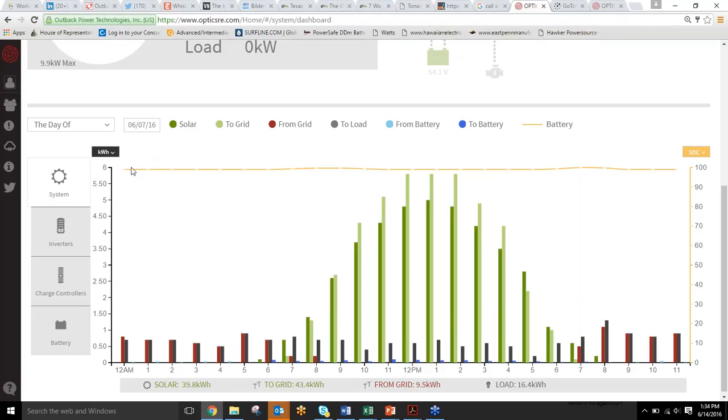And then at the top here, you've got your battery state of health. Right now we're going by state of charge. That means he's got a SNDC in the system, the FlexNet DC. That's also the piece that we were talking about earlier as far as more closely manipulating the SolarEdge inverter for a better charge. Essentially it's measuring amps in, amps out instead of just voltage to understand the health of that battery.